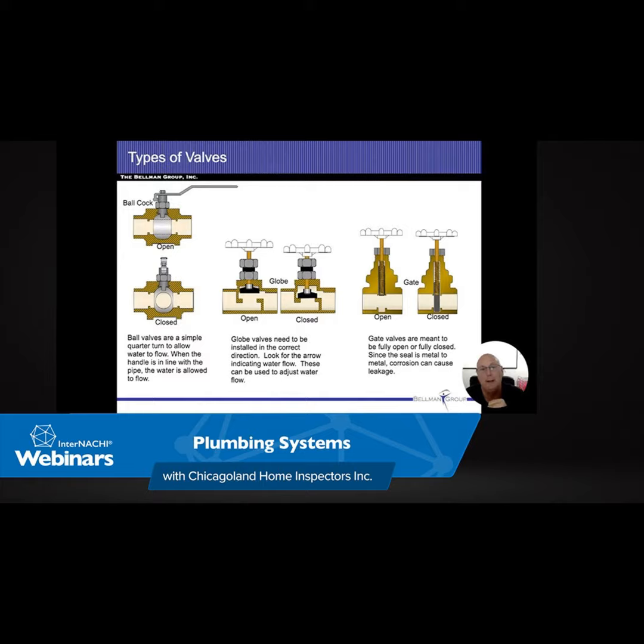These are the air gaps that are found in dishwashers and stuff. Nobody ever does this. I've seen pictures of them. I think I was in one house where I did actually see somebody install it this way, and it was with the Formica countertop. Sure enough, the countertop was damaged from water right around this thing. The water comes out of those dishwashers so fast that sometimes it overflows these things. That's all there is to it. So around here, it's just been a common practice not to do it. But nonetheless, I want you to be able to recognize it if you see it.